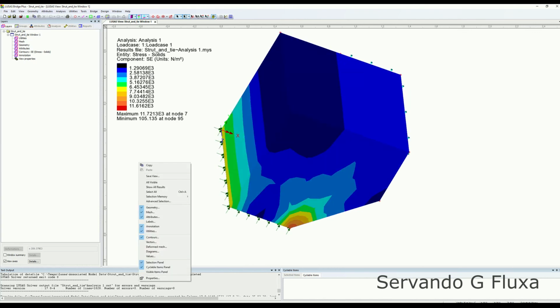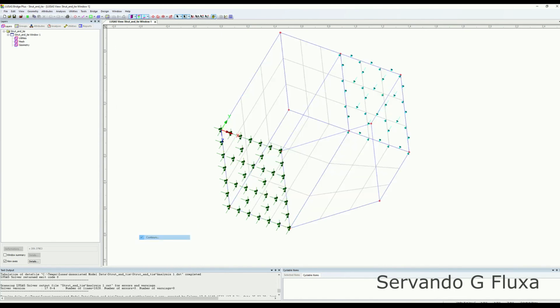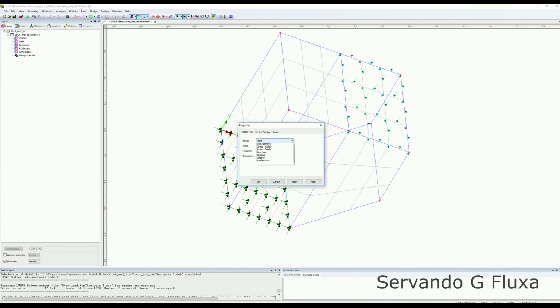What we were looking for were the strut and tie things. So we're going to go to vectors. Then we want to plot stresses, principal, average, nodal, or Gauss points. The Gauss point option is a little bit more detailed, because it generates intermediate points.